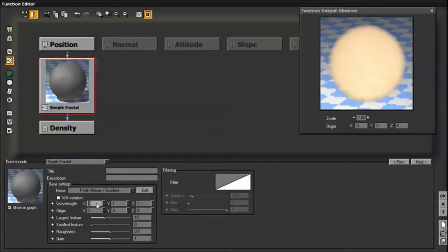And let's just go ahead and edit this. I'm going to change our wavelength. Since we're working with a smaller object, we're going to need a little bit of a smaller wavelength. I'm going to bring this down to 0.2 on all of our axes. And actually, if we take a look, our z-axis is currently our up and down axis. And because we're working with fire, which is a little more stretched on that specific axis, and we have the flames reaching upward, we want to make that setting larger than the other two. So I'm going to create 0.4, and now we can see that showing up already in our preview.